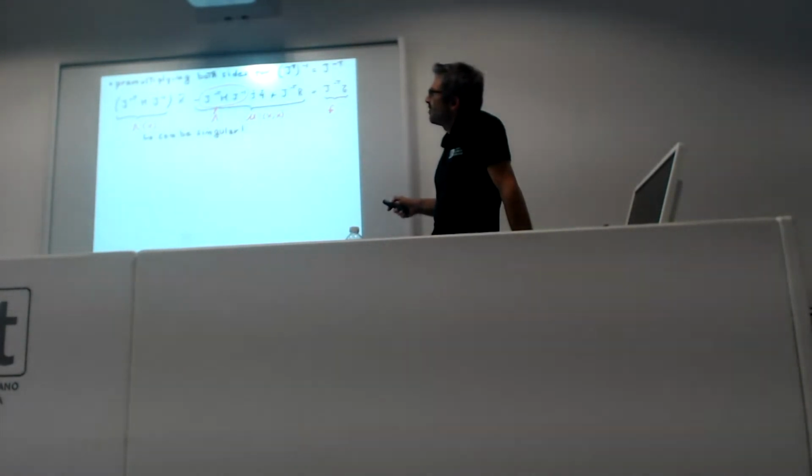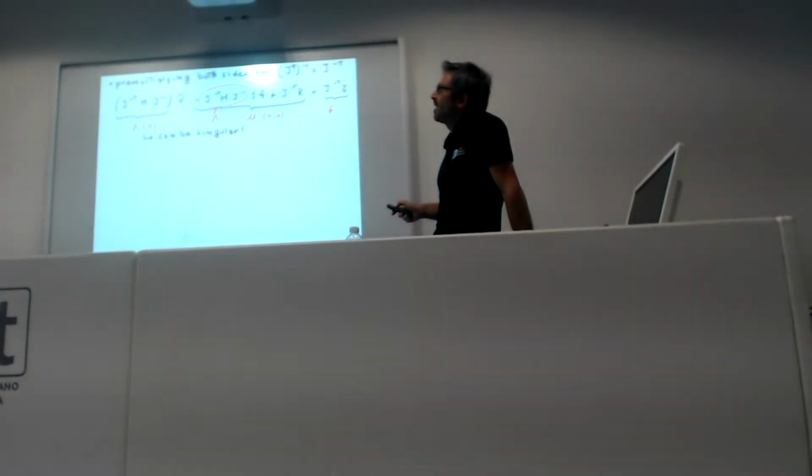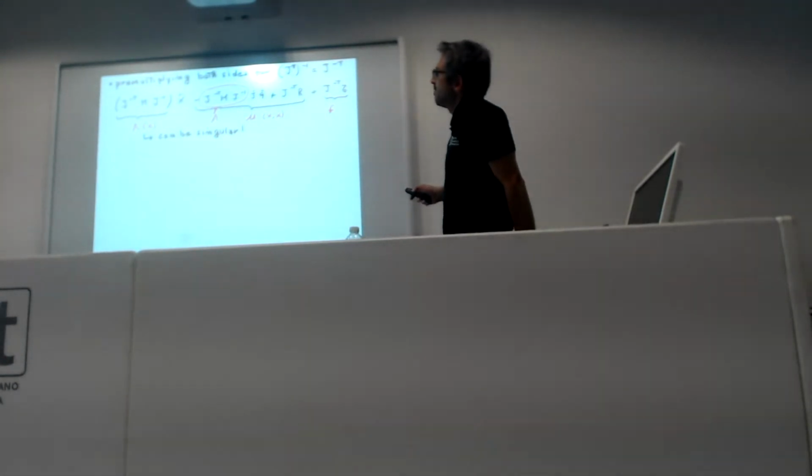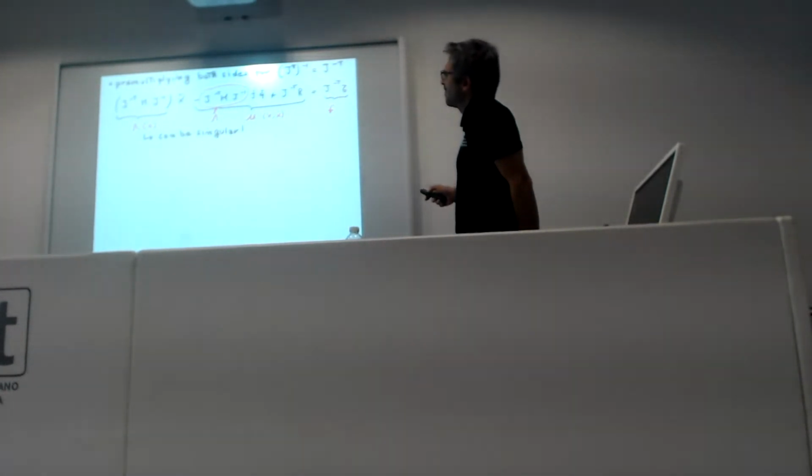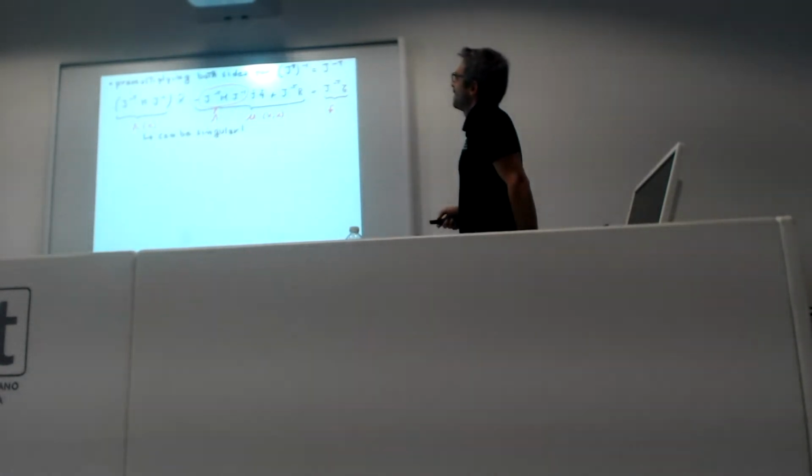Then you have something that multiplies the end effector acceleration, and is going to behave like an inertia. It's the operational space inertia, plus we have a very complex term that we call mu, that contains all the bias terms, the velocity-dependent terms due to Coriolis and centrifugal forces, and then on the other side we have the end effector force.